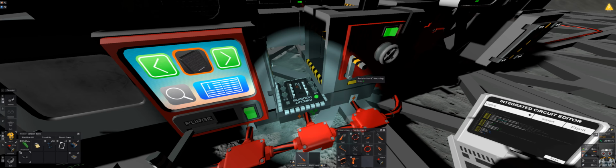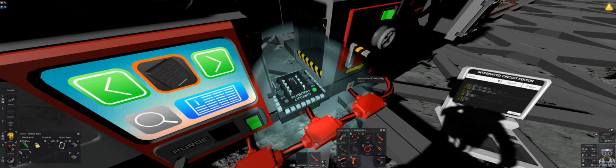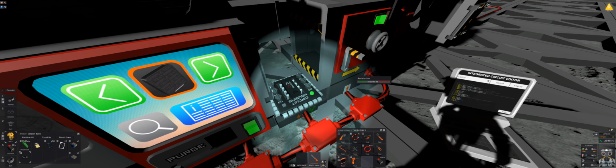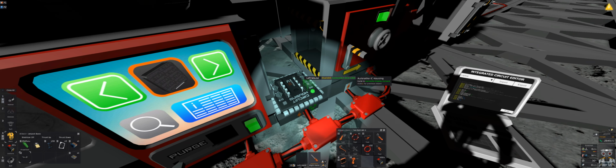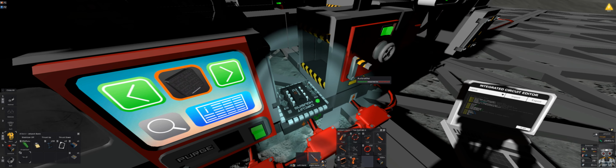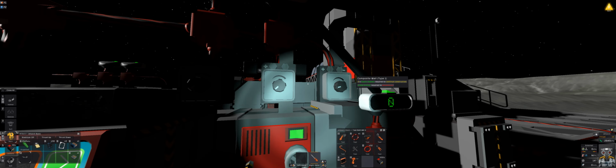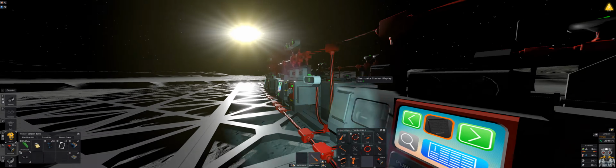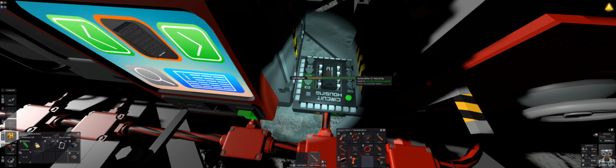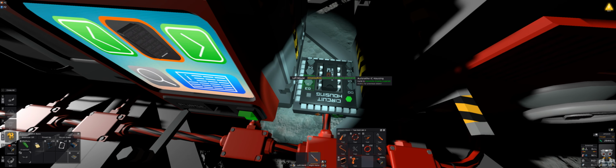So I wanted to show you these pins. There are some settings that you do have to place to pin. So D0, and again, once you hover over it with your screwdriver, it should tell you what it is. So there's your dial 100, dial 10, and your dial 1. It's helpful to name these dial 1, 10, or 100 to help you align them to pins, especially when you have more than one printer. The other three are for your displays, D3 through D5.